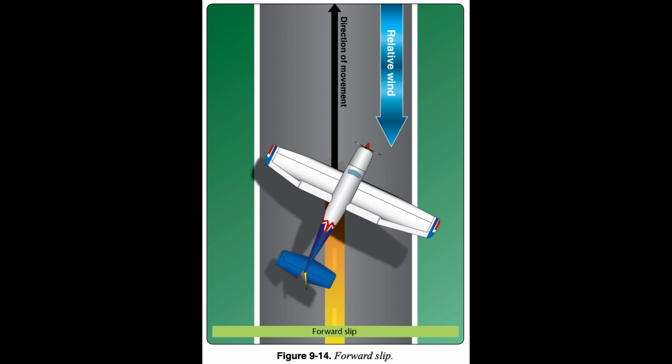In that situation, a pilot may initiate a descent using a forward slip much more quickly than by deploying flaps. To reduce the descent, the pilot can remove the slip without penalty. On the other hand, retracting flaps on an approach could lead to an unwanted loss of altitude. Even with full rudder displacement during a forward slip, the pilot can adjust to the left and right of the intended ground track by increasing and decreasing aileron deflection. The value of the maneuver explains its inclusion as a task in the Private Pilot Airman Certification Standards, ACS.